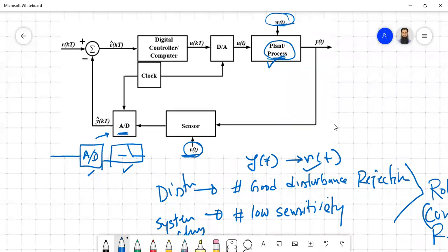What should be the size of the number sequence? It depends on the size of your ADC, whether it is 8-bit, 16-bit or 32-bit. The higher the ADC bits, the more expensive it is, so you have to be careful about this. You may want more precision, but if it is a high-bit ADC, then the storage size should also be higher. Whatever data you are saving will require more space. This is one common thing you have to keep in mind.